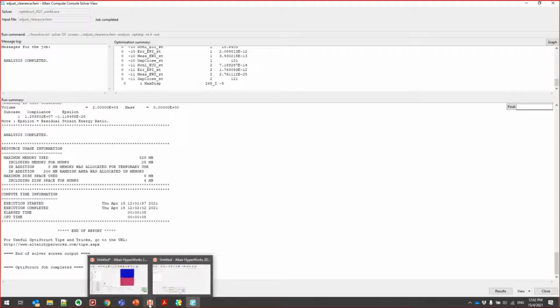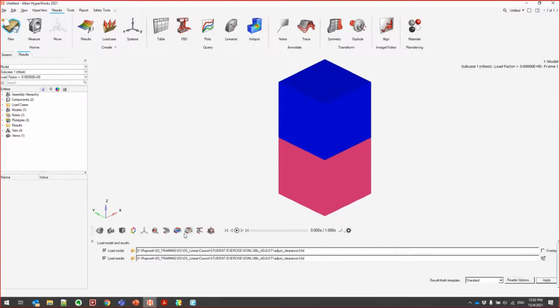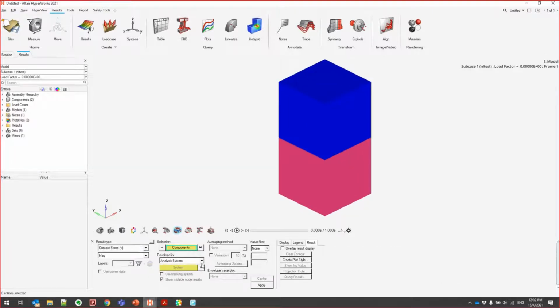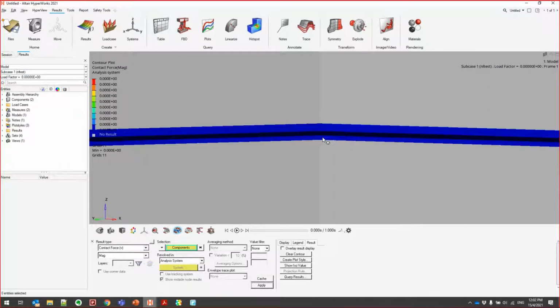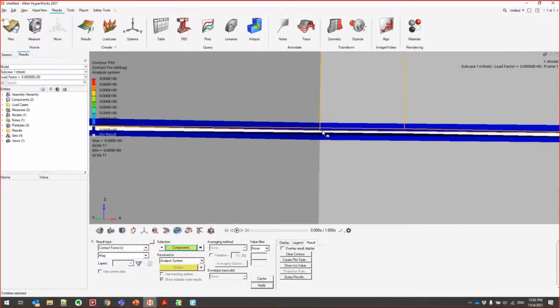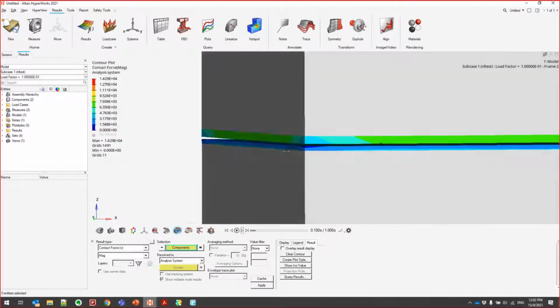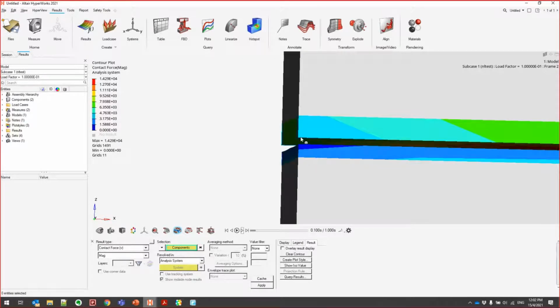Now you see at the beginning there's no contact force because there's a gap of 0.1, but my clearance is 0.05. As it moves to the next step, even though geometry-wise there's still a gap, the contact has been established because of the clearance.